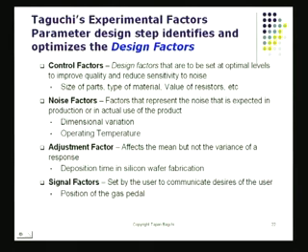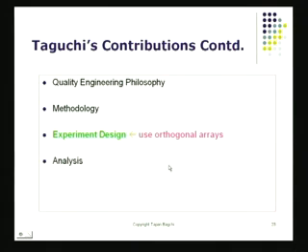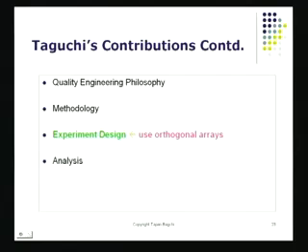And Taguchi clarified that almost every system will involve these factors. It's our job, the quality engineer, to make sure that we understand these factors. How do we basically find the right settings? And for this, Taguchi provided a method. These methods utilize a special matrix structure for the settings of these different parameters. That is done by what we call the use of orthogonal arrays. I'm going to be giving you some examples of this.